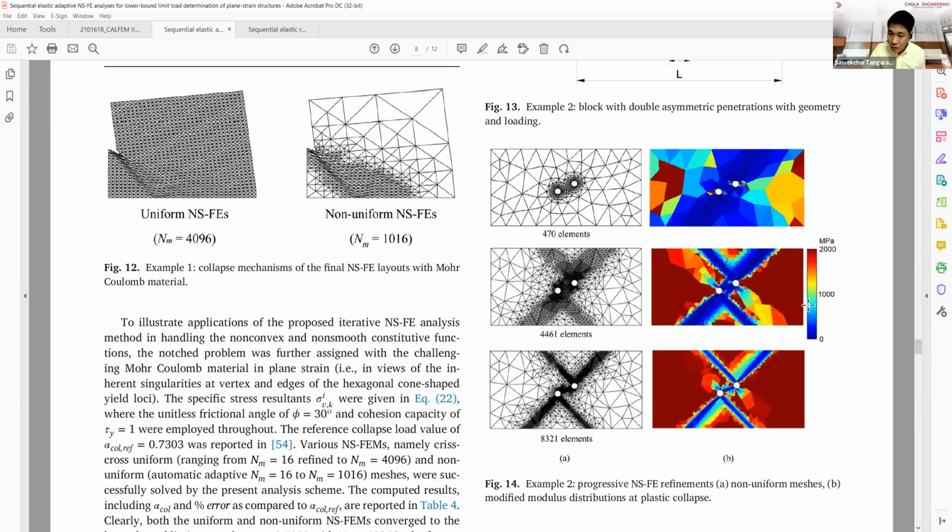And what I plot here in my exercise is not the straight stress value. I plot the Young modulus, but I use the elastic analysis. When the Young modulus starts to be low, it means the stress starts to develop up to the plastic stress. When the Young modulus is high, it's an elastic stress, right? Just think about the stress-strain curve. In the beginning, you have a high value of the Young modulus because it's still elastic. When it starts to lose the elasticity, the value of the Young modulus starts to drop. So it's close to zero. When it's zero, you're on the flat curve. So that's why I plot the value of the modulus variation.